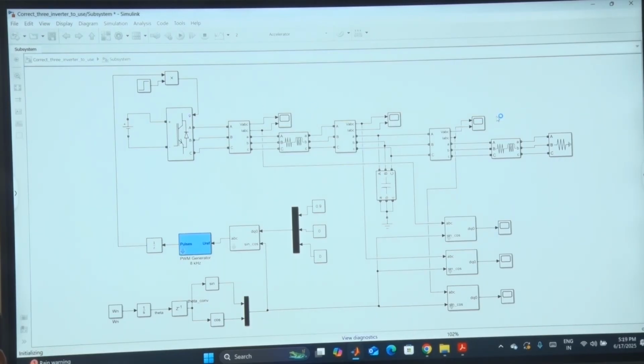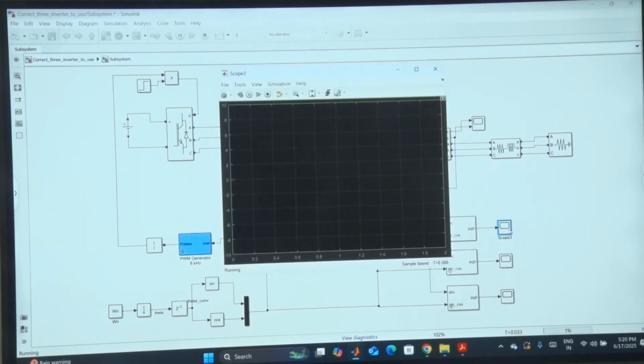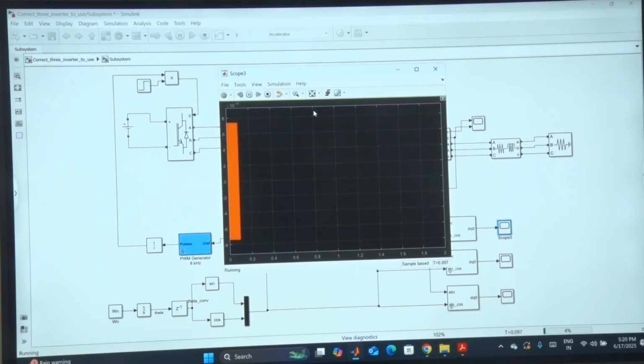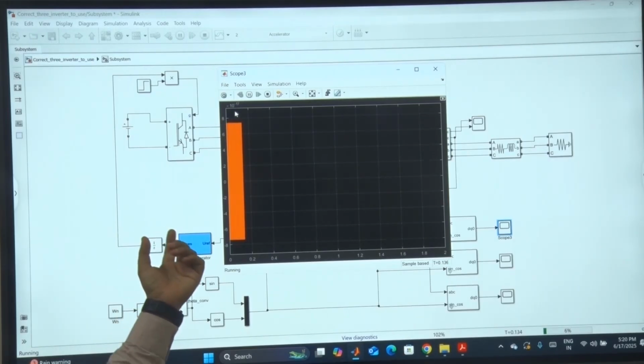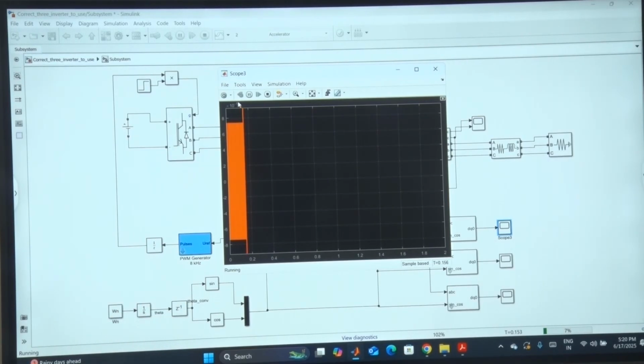Now if you run it, the AC variables we have received will be converted to dq0 quantities. First we will get the dq0 of the inner current IL, then dq0 of the output voltage, and dq0 of the output current. This number that you see is 0. It can't be read, it is 10 to the power minus 17. It's basically 0.